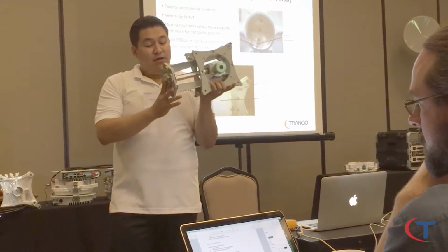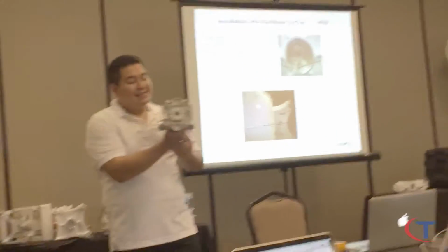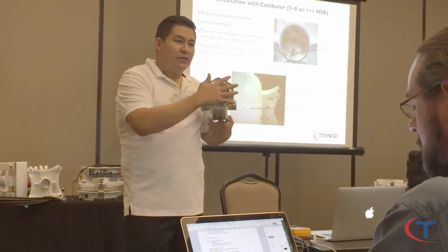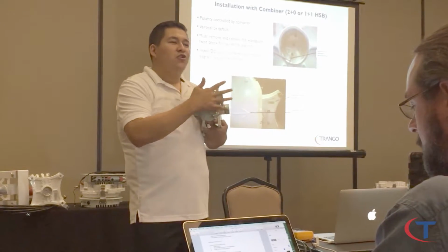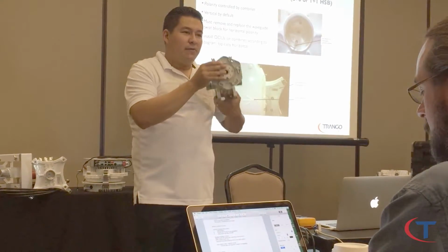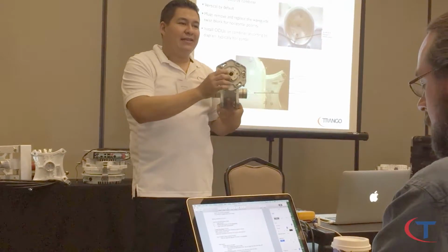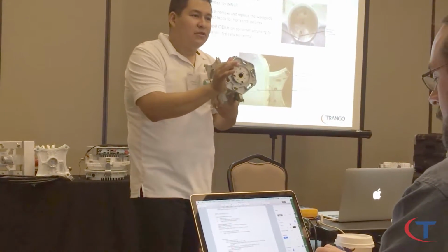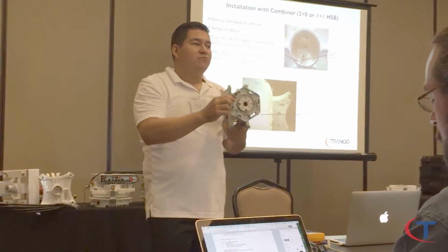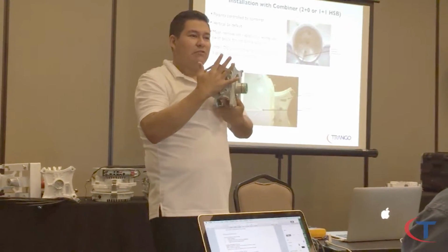Okay? Again, also, seating this on the back of the antenna, if this is not well seated on the back of the antenna, mounted properly, your link is going to degrade dramatically. So when you put this on the back of the antenna, make sure the seals, the gaskets, everything that's in here, it's properly sealed. I don't mean ratchet down all the way until you crack it. No, just make sure it actually seats properly there.